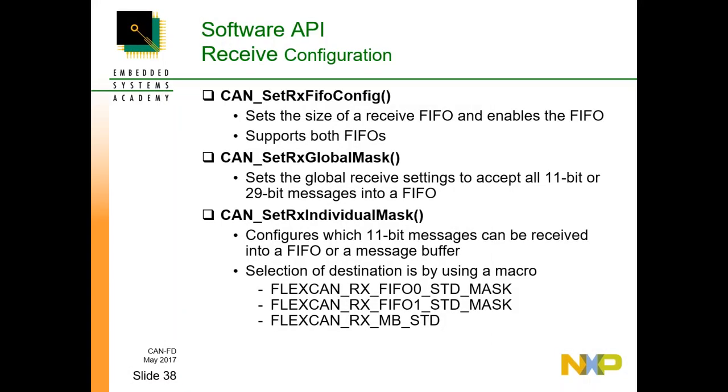These set of functions configure how and what can be received. Use of the FIFOs is optional, and if either of the FIFOs are to be used, then set RX FIFO config is called. This sets the size of a specific FIFO and enables it.